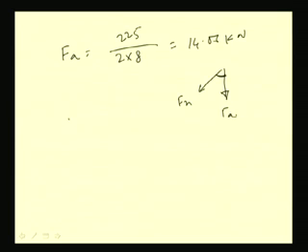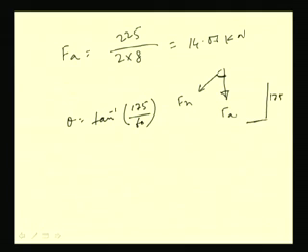So, theta will be tan inverse 175 by 60, because the outermost rivet vertical distance is 175 and this horizontal distance is 60. So, theta will be tan inverse 175 by 60, that is coming 71 degree.